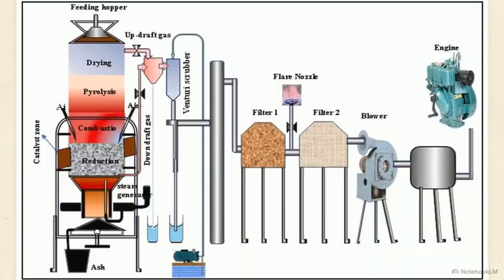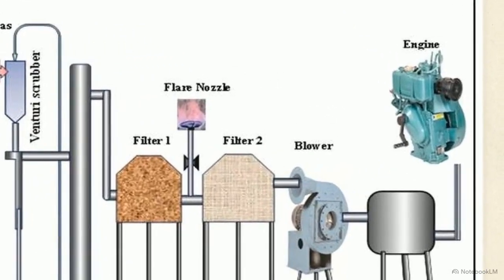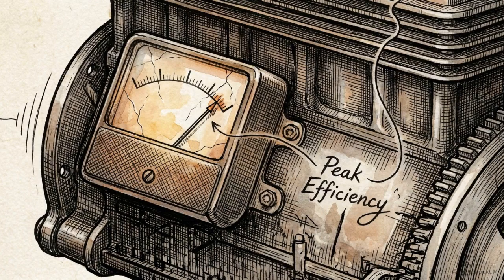The final phase connects the purified producer gas directly into the intake manifold of a standard, unmodified spark ignition engine. Because producer gas has lower energy density, the engine governor requires tuning. Setting the air-fuel ratio to 1.6 balances oxygen and guarantees stable combustion. Operating exclusively on pigeon pea gas with zero supplementary gasoline, the engine generates 4.4 kilowatts of power at a 16.8% brake thermal efficiency.